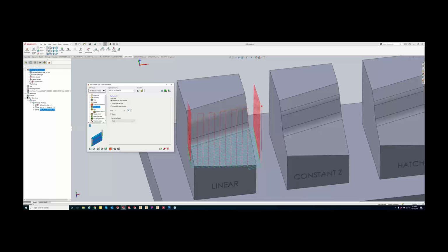And this is going to kind of come in handy if you guys are using more of a chamfer cutter and you want to shift that tool down and over. So we're not working on the tip of that chamfer tool. We can work more on the side. And kind of like what we talked about last week, we have several different tool contact points: auto, at center, radius, and front, so we can control it. Where the auto is automatically going to adjust that ball end mill or the bull nose end mill or even the flat end mill on what we're cutting there.